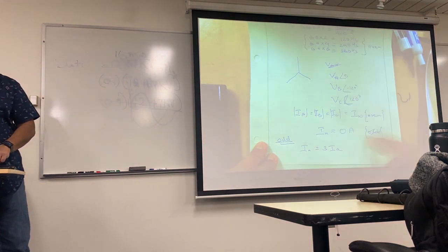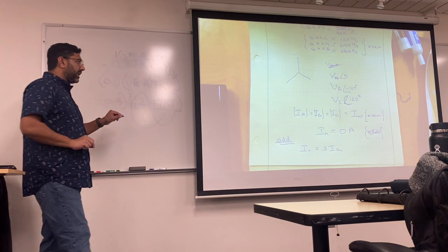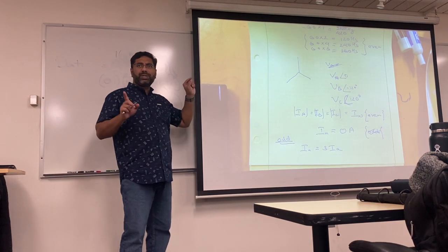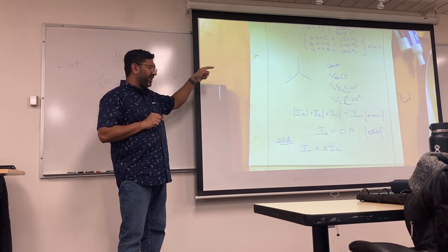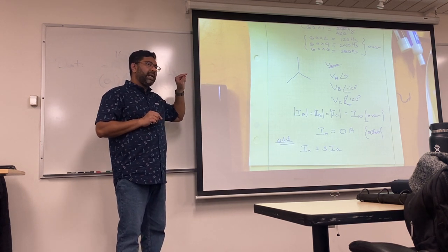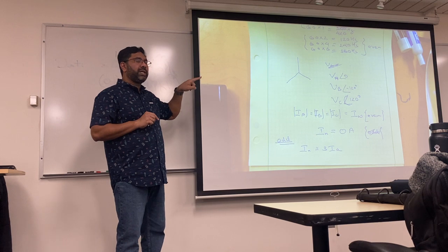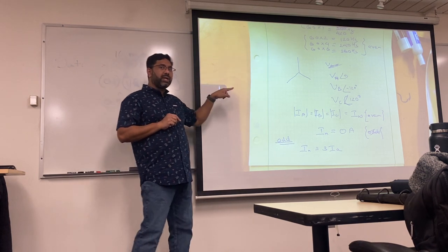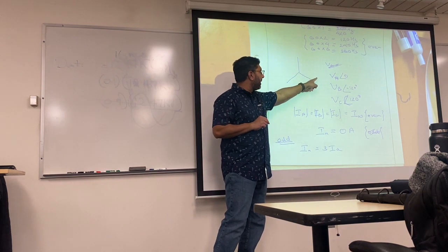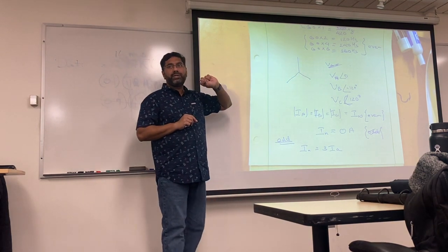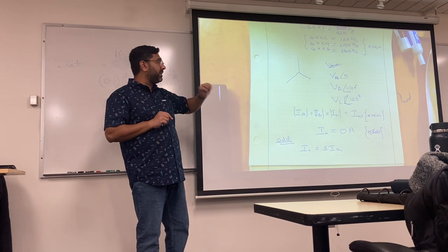This causes a lot of headache, because earlier I was showing you, in an email or a Discord message, about 3 wires and 4 wires. And at the end of the last lecture, I was saying, no matter what, expect your client to have the 4th wire, the neutral. Never leave it to them to do the right thing. They will never do it.